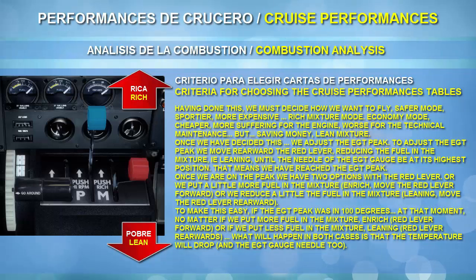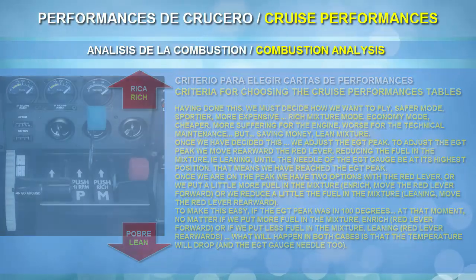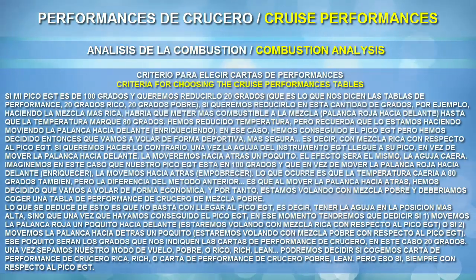Because we need our engine speed not to be limited in RPM. Let's imagine you have a problem when you are descending, and perhaps you don't have nice visibility, and you have to avoid landing, okay? In that particular moment, you will need to proceed with another maneuver, and you will need to have all the maximum power you can grab from your engine, okay? For that reason, at lower altitudes we need high RPM, the maximum RPM or high RPM, and the mixture in full range, okay?